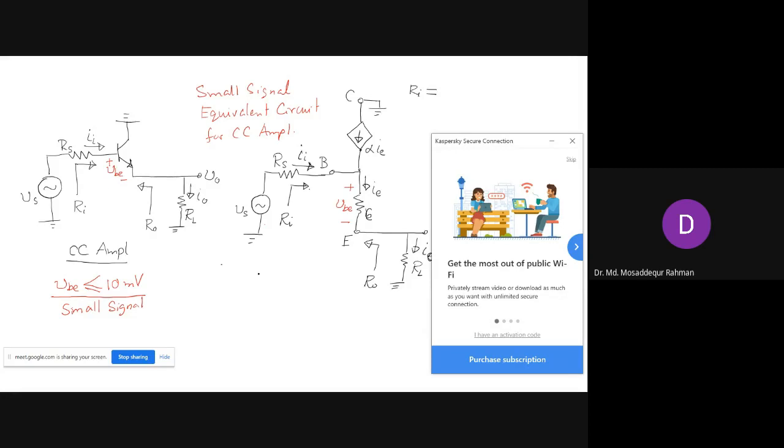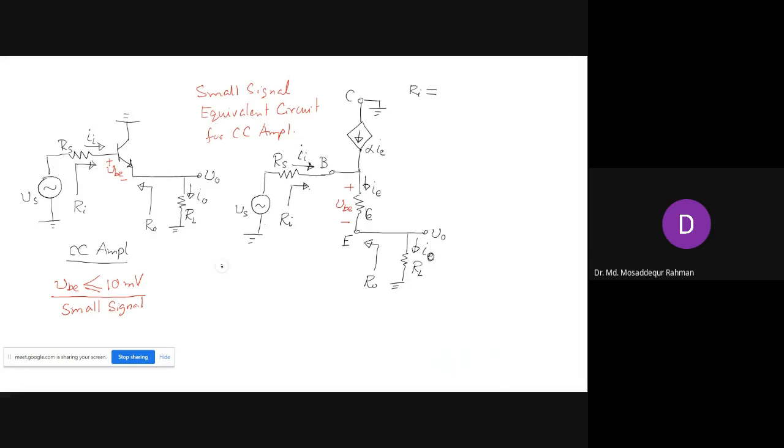When you are determining the gain, you see that RL comes in, right? The input resistance is between this point and ground. You cannot take a floating point, right? We are saying the input resistance at a particular point, so it is between this point and ground, with respect to ground. Here RL is grounded, so RL will be included. So what will be the input resistance?